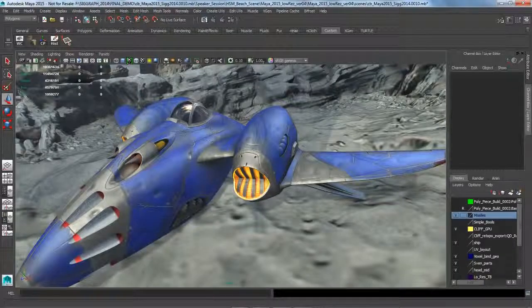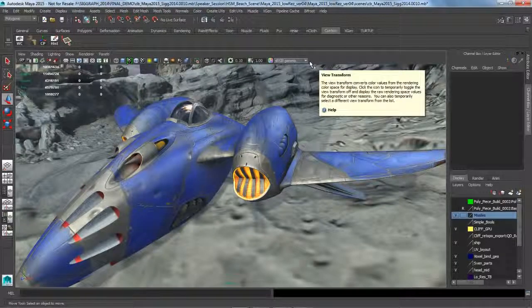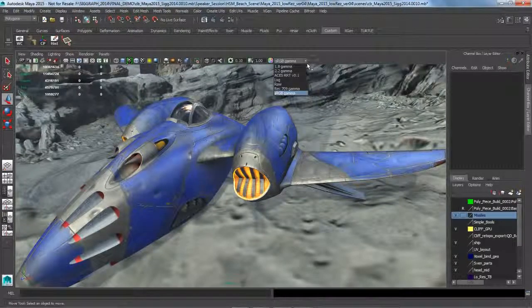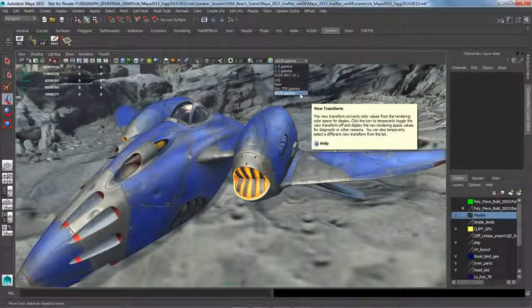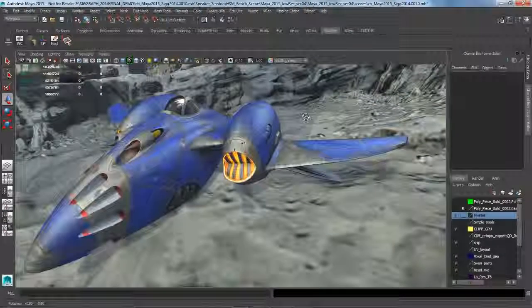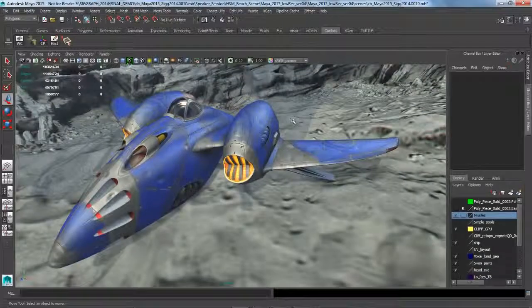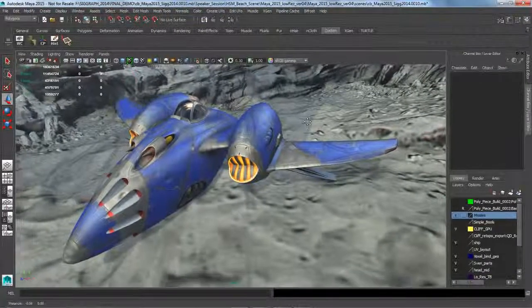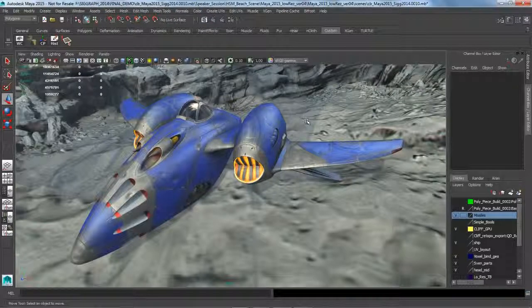And this is good for a couple of things. If I'm using a linear workflow for rendering, this is where I can match this working space within my viewport. So that's excellent for your rendering workflow, but also for a model visualization thing. So if you really spend the time to dial this in, you could really start to get some nice viewport effects to really showcase a model really well with things like ambient occlusion, full shadowing, adjusting your exposure and gamma on the fly so that you're getting something that's closer or in context to your final render.